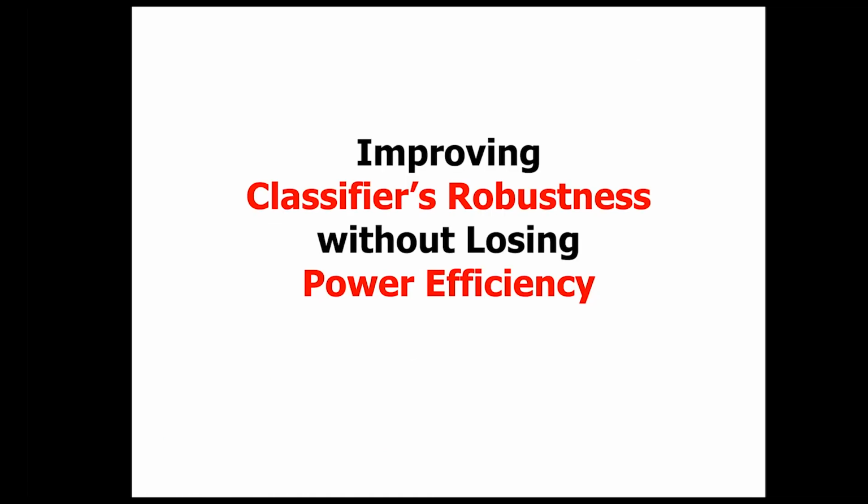Okay, so now we are going in a slightly different direction, but also very related. So far I've talked about how to reduce power consumption, and it ended up consuming hundreds of nanowatts, right? If you combine the analog programmable feature extraction, the A to D, and the classifier introduced so far, all together it is definitely less than 1 microwatt, right? So that's something we already achieved.